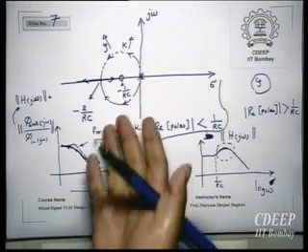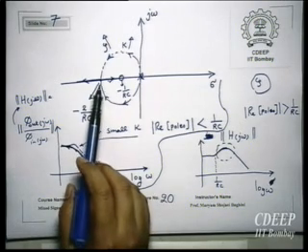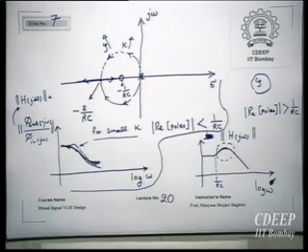Of course, settling time for imaginary poles is also very high; in fact, it is infinite, but the system is also unstable. Here, there is an optimum case for settling time because the system will be either underdamped, critically damped, or overdamped. When it is underdamped, it is slow. When it is critically damped, it is better. And when it is overdamped, it will be faster. But if you increase it too much, then actually it will become slower because it will take time for this ringing to settle.